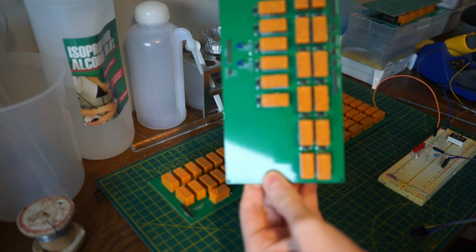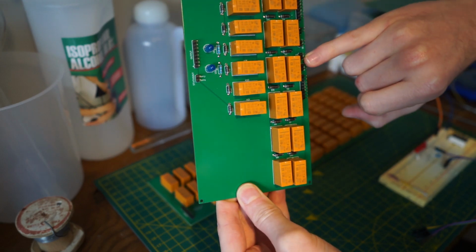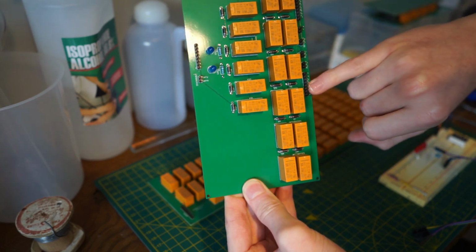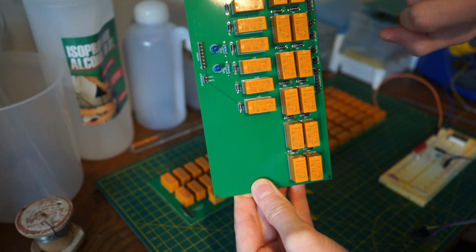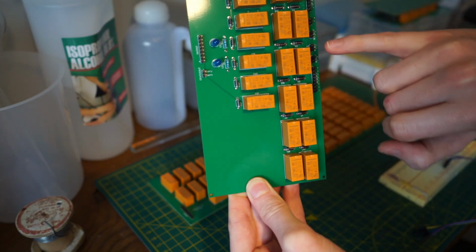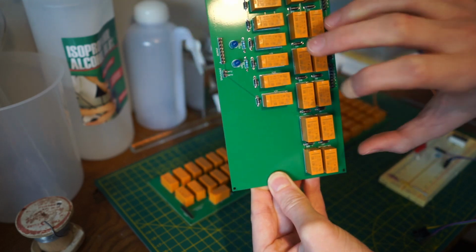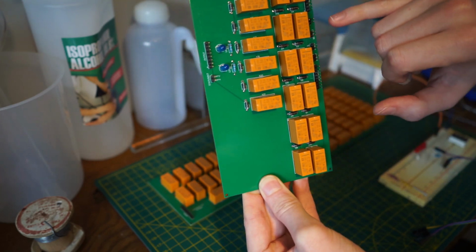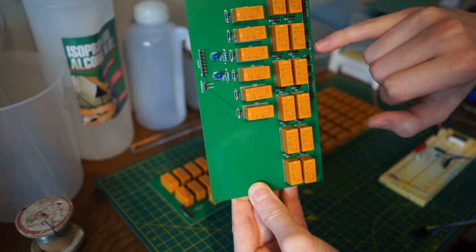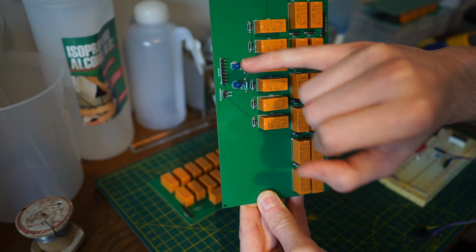It will be this way around. You have your two inputs, and you can select which of the two you want. So if you want the logic, it's there. You would put a high pin on the logic select, and it would switch to the logic. By default, it's always going to output the arithmetic board to the bus, which will be connected to here. You have your enable, so only when this is enabled will it actually output to the bus. You also have your carry in. So you have your set and reset pins for 2 1-bit registers, which are your carry and 0 flag.